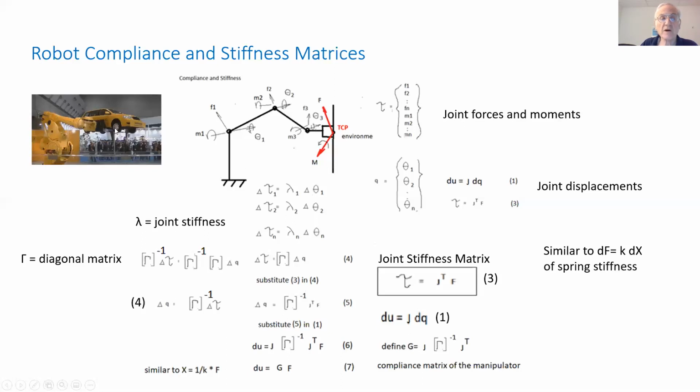Or if this robot is pressing against a workpiece, we can also find the force which we apply just by measuring the displacement. That can later be used in a machine learning program which could control the variables of the servo system of the robot.